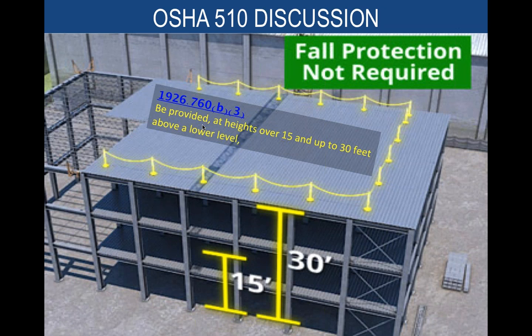Also, walk around the scaffolding areas, right? If it's necessary to work around raised platforms, we have to be sure that the work site is covered and protected. So we don't want to be walking under scaffolds unless it's being made for traffic through underneath the scaffold. Okay, easiest way to tell is if we're having to walk over any type of cross members, any type of bearers, or anything else like that.